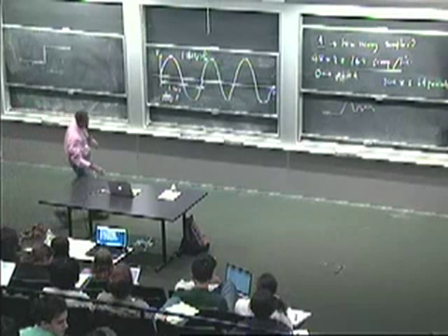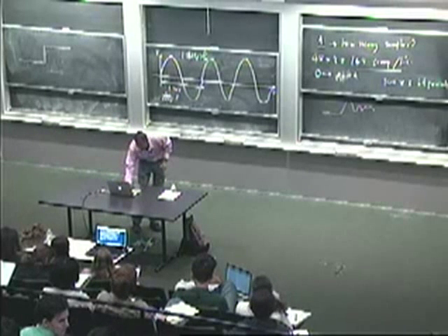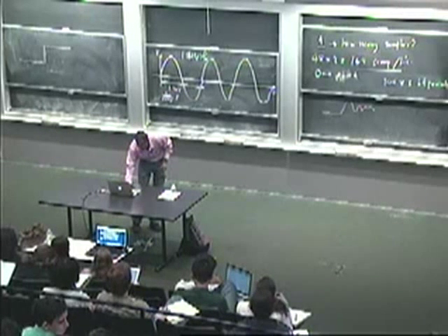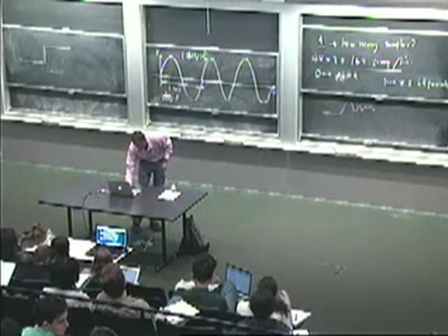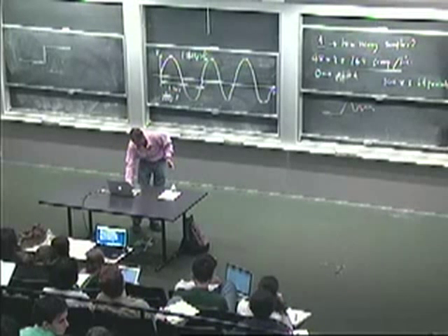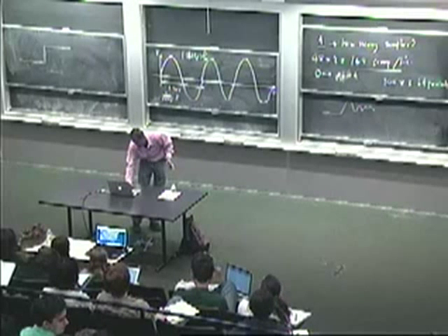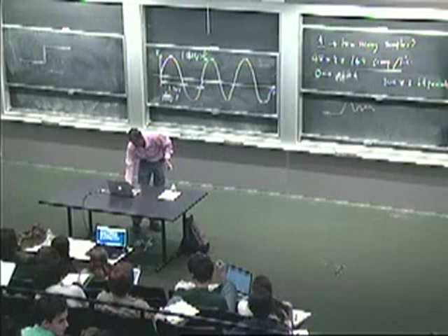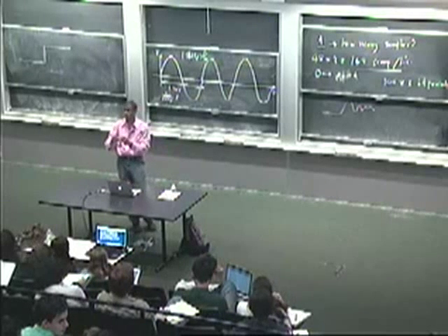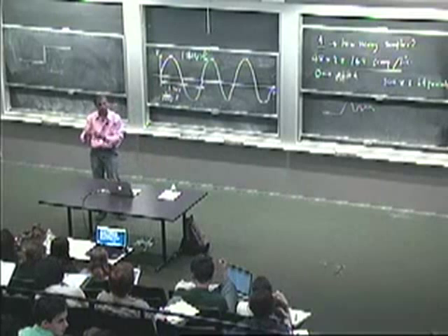The receiver can decide that when a 1 happens, it corresponds to something over here at 0.35 or 0.4 volts. When a 0 happens, it may correspond to something like 0.1 volt here, which means I can pick the middle point and slice it there to determine whether the received bit was a 0 or a 1.